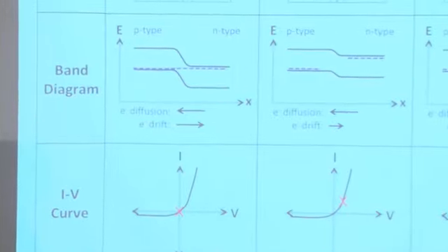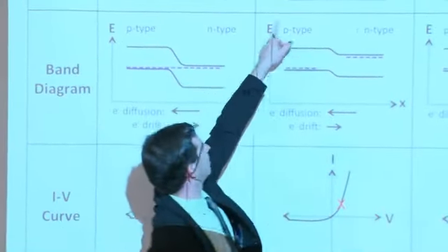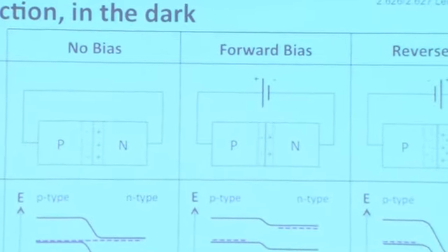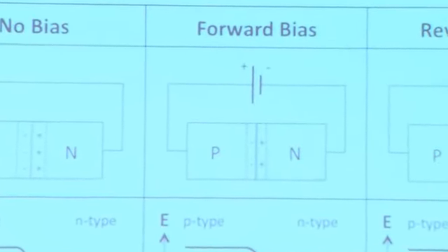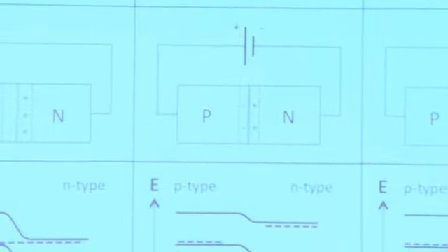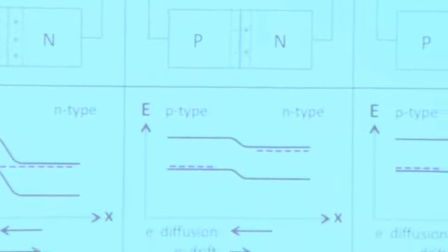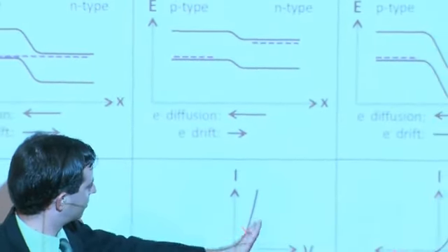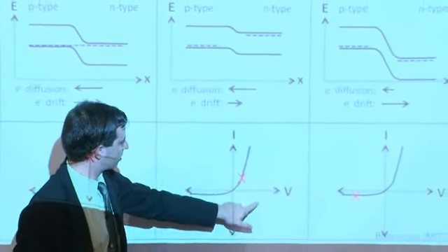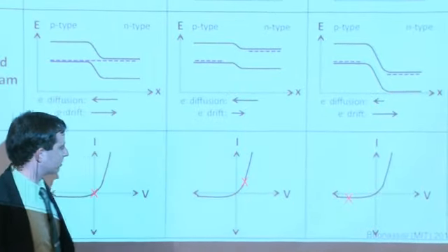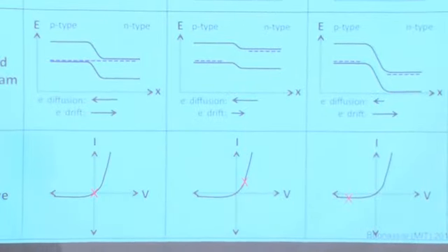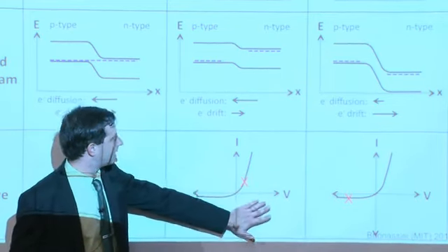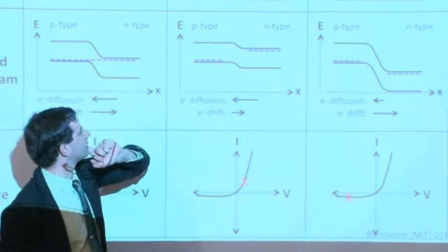Because we're adding a resistor in series to our solar cell, instead of a battery there, you would replace that with a resistor. Or if we're applying a bias voltage as well, we could also do that under illumination. So we'd still have the illumination current, right? And we'd, through superposition, shift this entire curve down. We'd be operating somewhere in this quadrant right there, right? So this we call fourth quadrant, typically 1, 2, 3, 4, fourth quadrant. This is where power is coming out of the solar cell device.